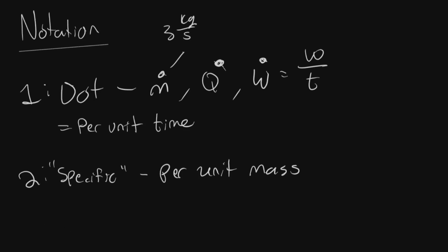You might have also noticed that I write the volume with a line, and that's because we have volume, which is a capital V, and also velocity, which sometimes is written as a capital V, which is really annoying, but I think it makes more sense as a lowercase v. And just to distinguish all of these, volume gets a line through it, it's a little bit easier. Specific volume is volume per unit mass. So this is just equal to total volume over mass.